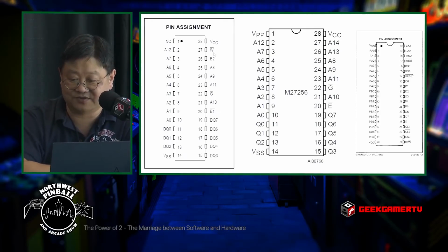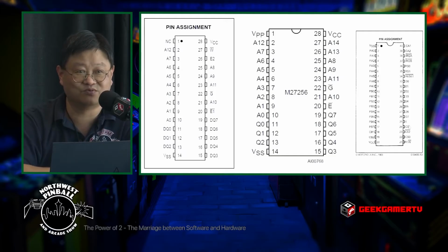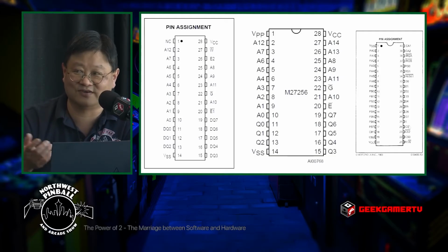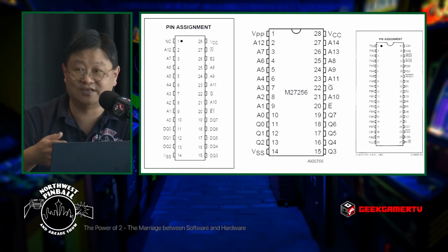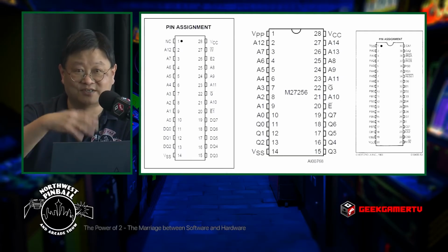So you may ask yourself the question, well, why would I care to have, like on the PIA, three signals? Why not have just one? Because I'm either active or I'm not active. The reason for this is that it allows the board designers to send different signals if they do and don't want to activate on other signals. In essence, it's built-in address decode on that chip. You don't need to supply an AND or an OR chip that's sitting off on some other part of the board.